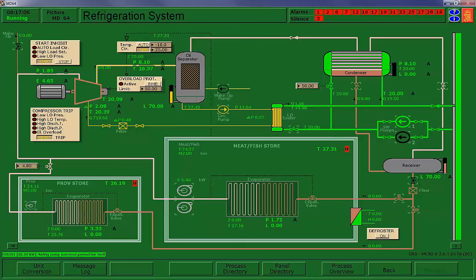Right now we've got about 1.7 bar suction pressure and 8 bar discharge pressure. And again, that high pressure coming into the condenser, what that's doing for you is raising its saturation temperature above the saltwater temperature so we can condense it. All right, we're down to 1 bar. I'm going to go ahead and put the liquid on and put the control in automatic. And it should run itself.